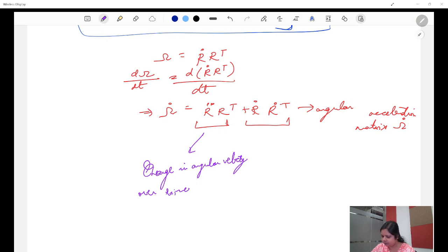So angular velocity change over time. This is all it is. This is a new extra term that is arising, and it arises from the product rule, because we had a multiplication, we differentiated and everything from the product rule. And what it represents is the rotational coupling effect.